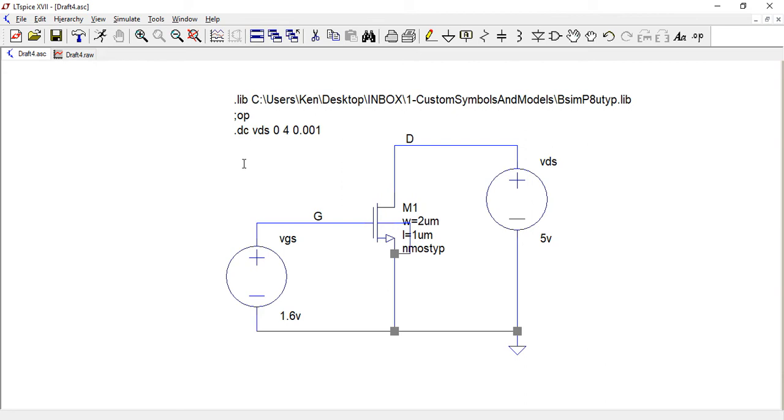The next one is measuring or observing the behavior of the transistor for different process corners. And what we mean by that is you're going to have normal process variations, and one of the parameters we're particularly interested in is the threshold voltage. And it will typically vary from around 0.7 for the minimum model representing the process to around 0.8 for the typical model and around 0.9 for the maximum model. They're just ballpark figures. So what we need to do is we need 3 models now, not just a typical model, but we need a model for the min and the max of the process. So let's have a look at that.